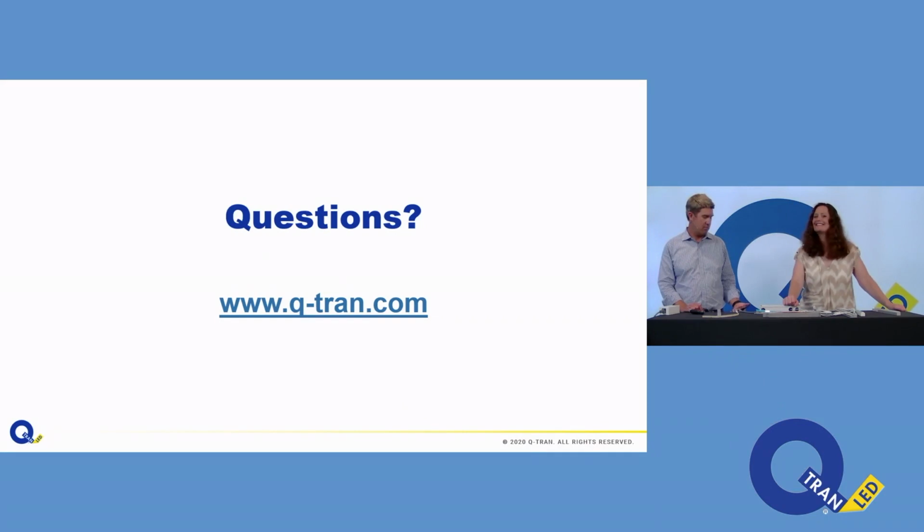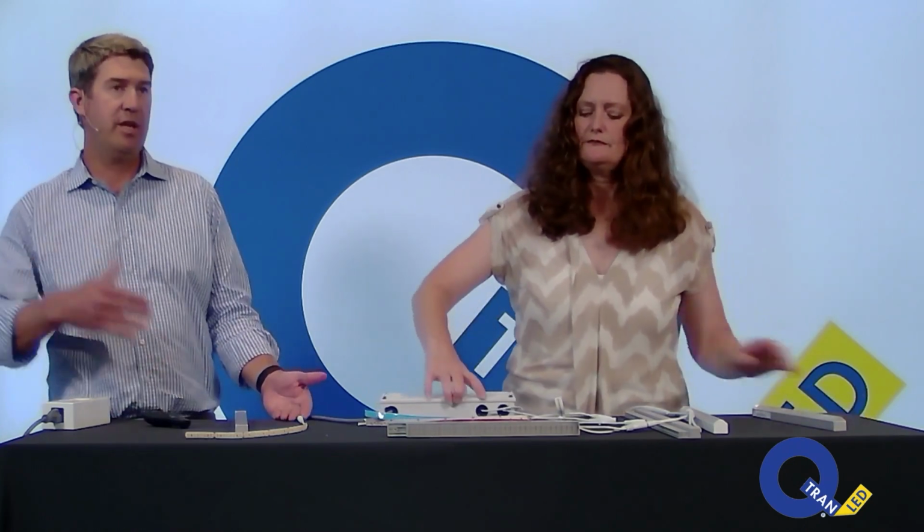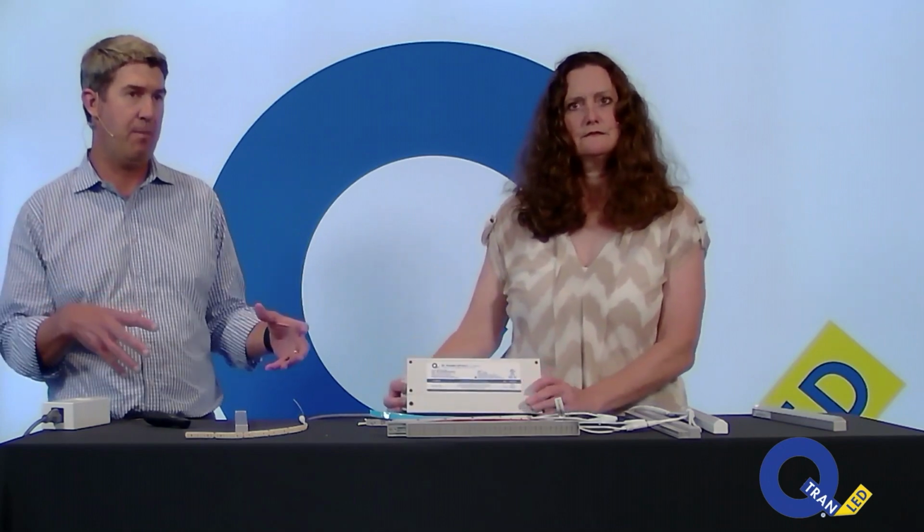Do all products dim the same if used in the same area? When you use our QZ power supply, the pulse width modulation dimming protocol mitigates inconsistencies across products to even out the dimming curves. So that's my long yes. So yes, we can do it. We can have QZ, SW, HE, and HE Plus in the same space on the same power supply on the same dimming circuit, and it would all dim together.